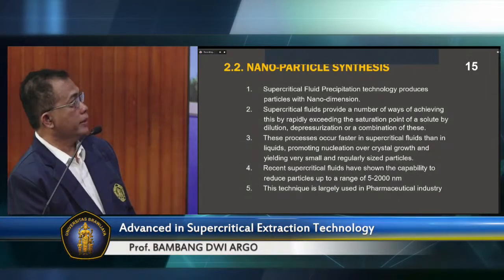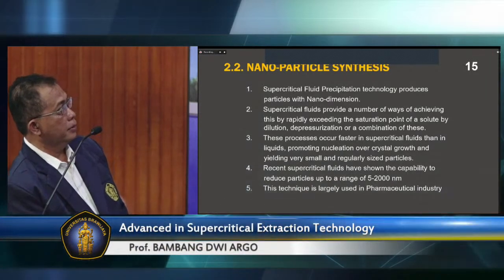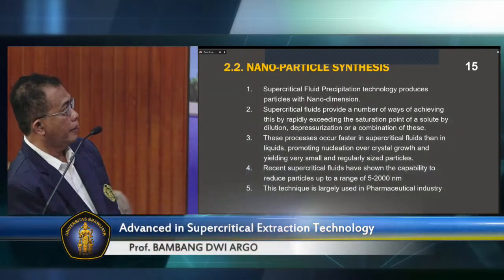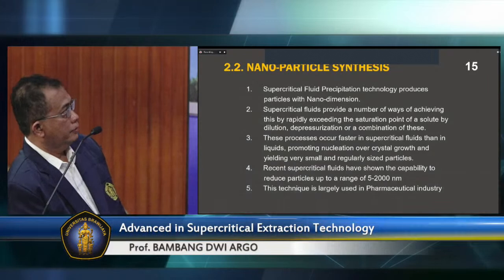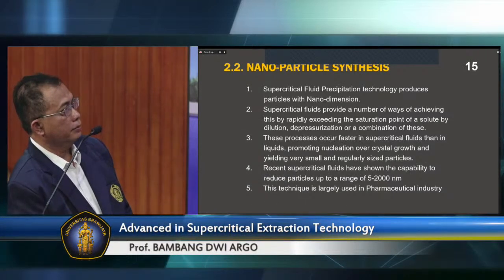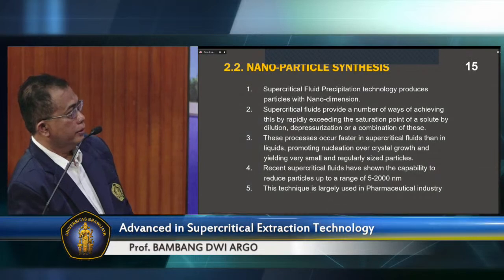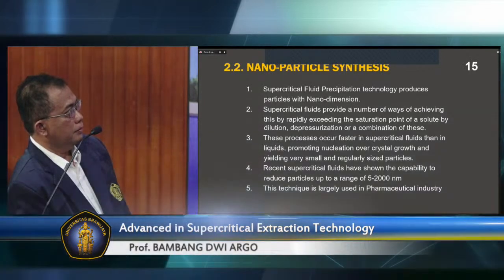The first is that supercritical fluid precipitation technology produces particles with nano dimension. Supercritical fluid provides a number of ways of achieving this by rapidly exceeding the saturation point of solute by dilution, depressurization, or combination of these.